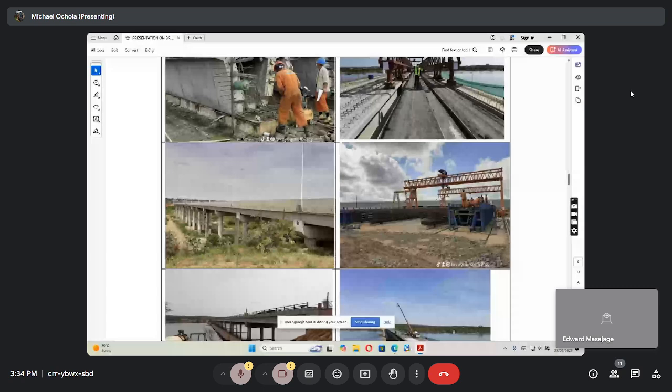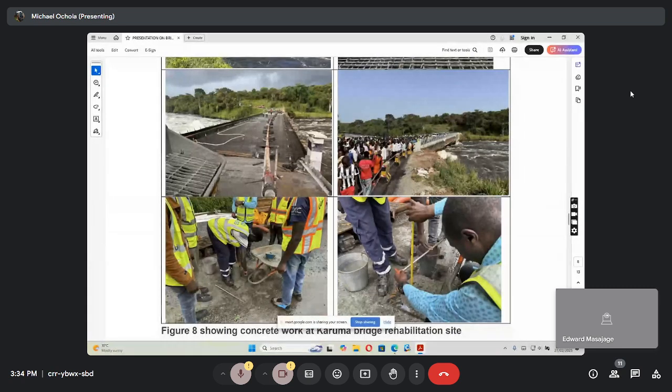So it's about 5 kPa. The code allows you to limit at 5 kPa because this can happen. If there is a war, people can go. If there's any function, like if your structures are near a stadium, where there's a lot of excitement, this is what you expect on the bridge. And you guys will do dynamics; if a resonance happens on the structure, like footbridges, definitely it can go into something else. But we shall get into that when you look at vibration and dynamic response of the structure.